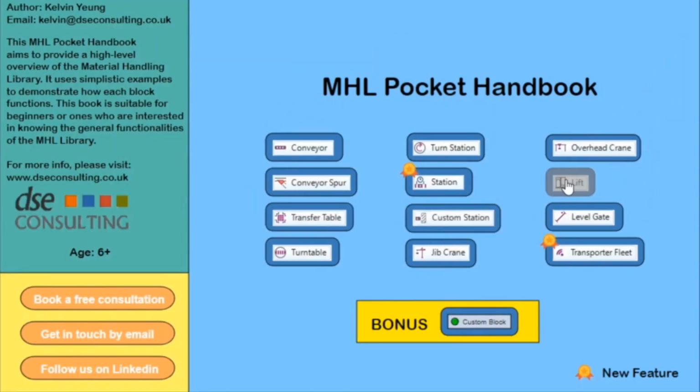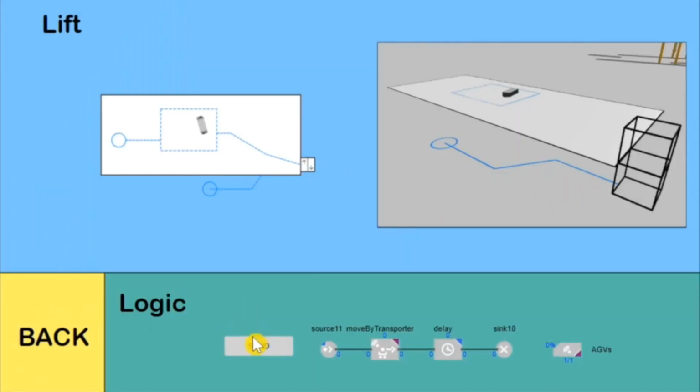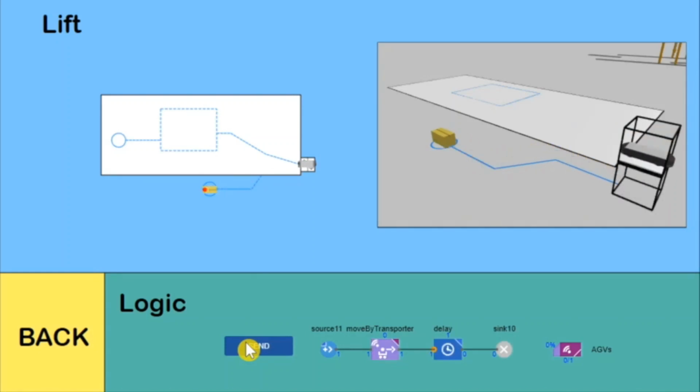The lift. The lift is a space markup shape that graphically defines a vertical reciprocating conveyor. And at the moment, only 2 types of network support this element. They are the standard process modeling library and the MHL library. Transporters with free space navigation mode can enter the lift from any side, and to restrict their movement, we need to draw the walls which will impede the movement of the transporter where it is necessary.